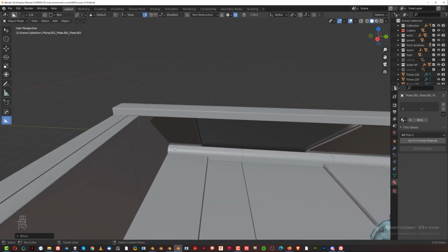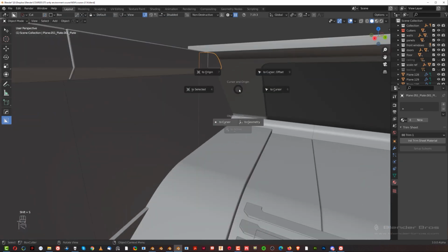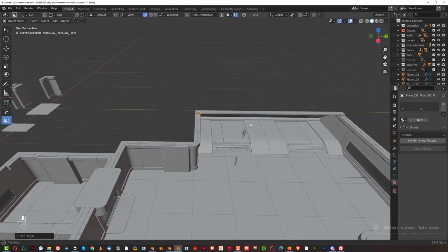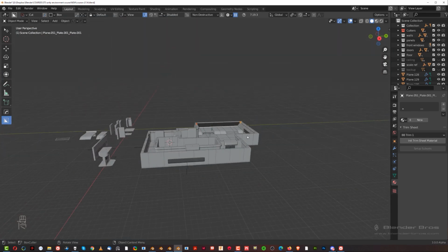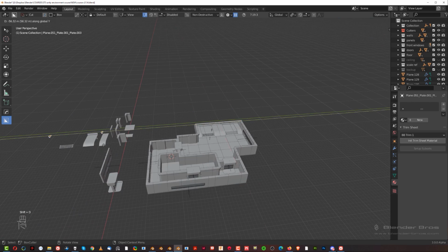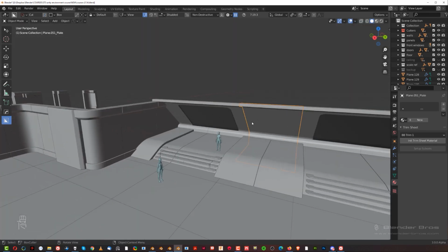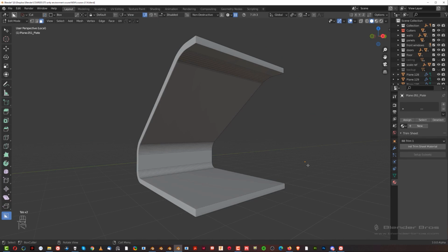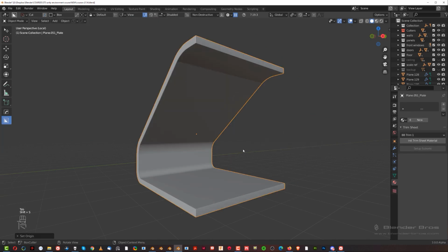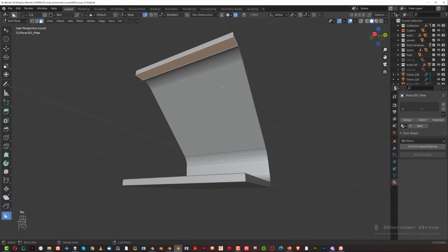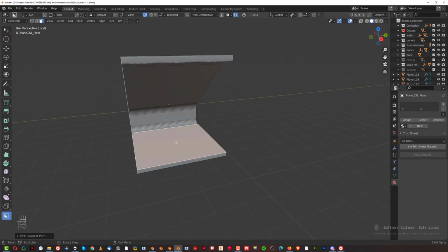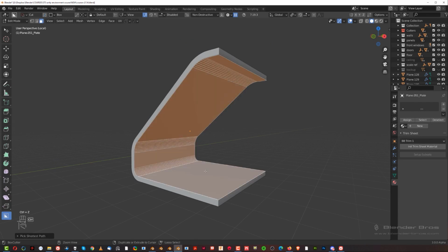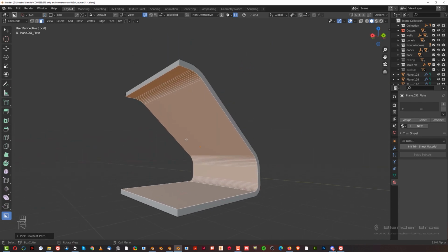That's how easy it is. So here, Shift S and to geometry, and of course we need these pieces. We're going to move them on the Y axis over here, and this one we're going to move over here. Now we're going to grab this middle piece, go to local view, and remove this occlude garbage. Let's move this origin point back to geo, it's going to be better. By the way, we need to do this for all the pieces later on before we move on to Unity. There are a lot of things we have to prepare before we move to Unity, but it's not complicated, it's actually quite easy.